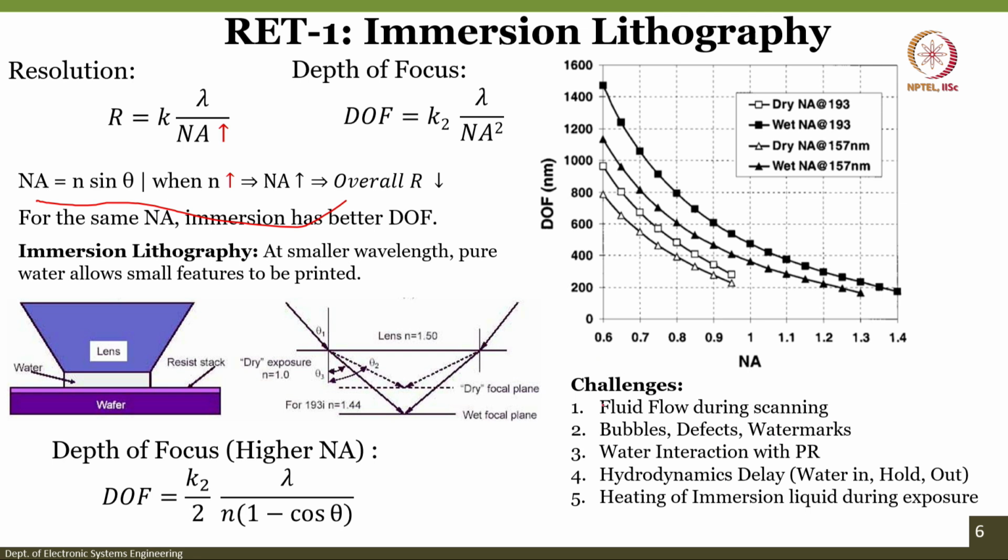And what are the challenges with that? First and foremost, we are using fluid instead of air while we are scanning or exposing. The important point in this case is that you have to put the medium in, and even the smallest bubble matters. Last time I mentioned that if there is the slightest change in design or mask or process, your device will get hampered and you will not get the desired pattern. I was referring to this as well. A small bubble can result in a defect in the mask and you might have to recall the entire device. So, it should be taken care of very cautiously.